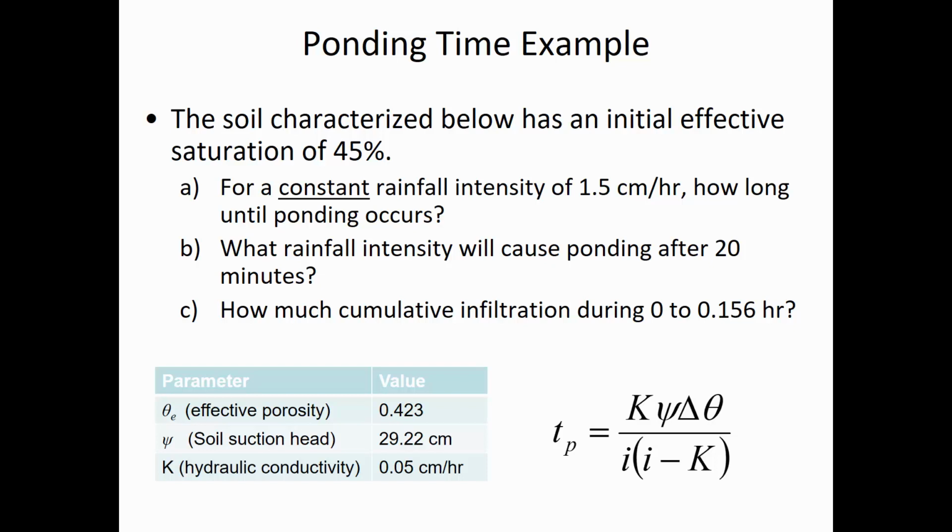Now, naturally, the time of ponding of 20 minutes is going to require which intensity? We have this known 0.333 hours down in the denominator. So this means that I squared minus I times K is 1.0207. That's the result of all of this. And so now we have an equation that we need to solve the roots for.